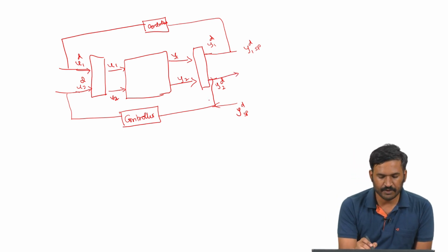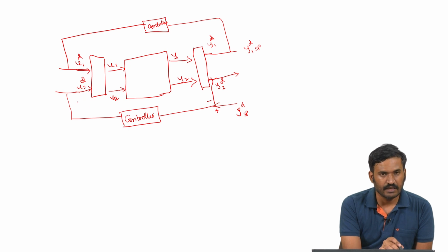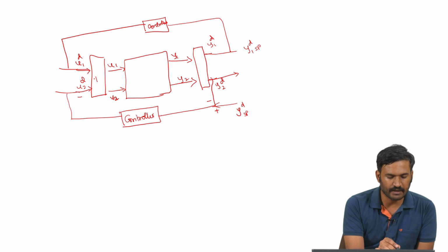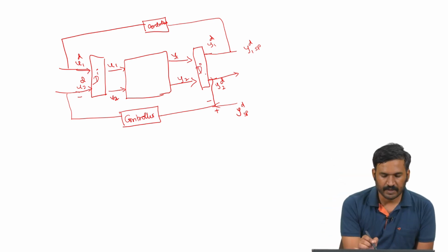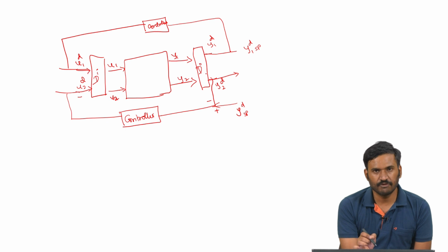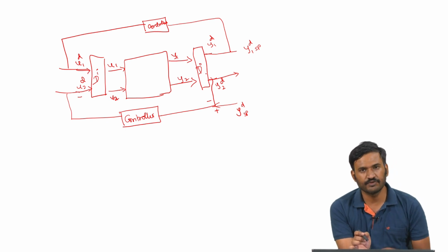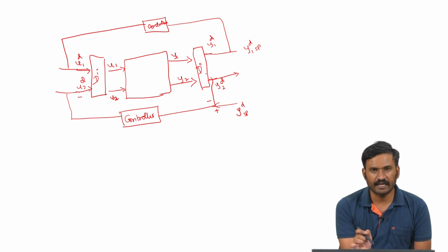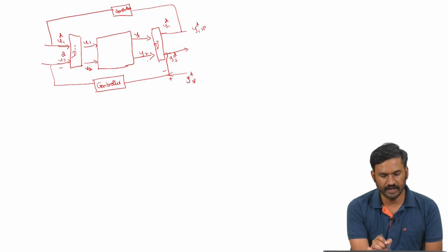Based on that, we compute the error, and the controller will give the corresponding decoupled U. So, we have a decoupler transformation for input and a decoupler transformation for output. By default, we choose the output decoupler to be identity, so that we have a notion of the set point as the objective of the variables y1 and y2.